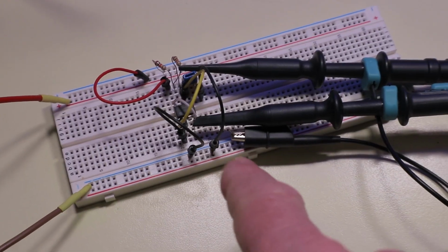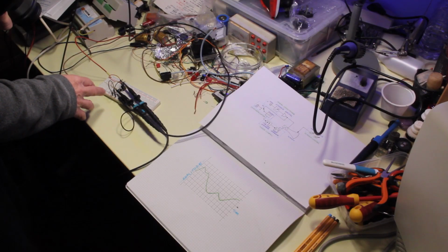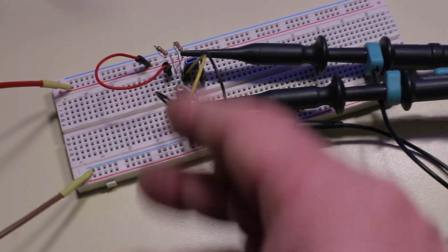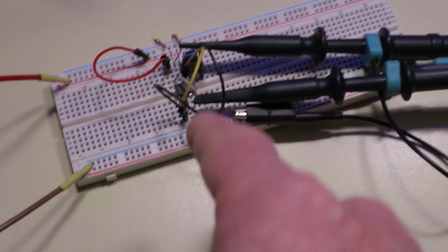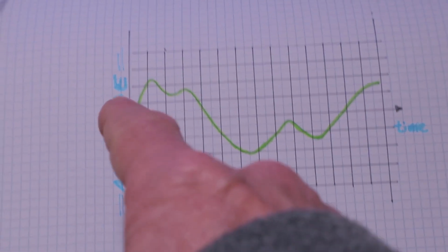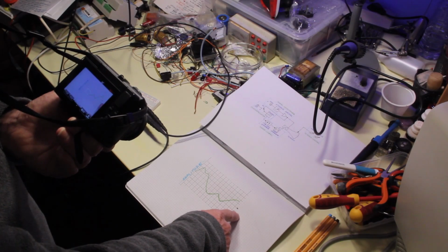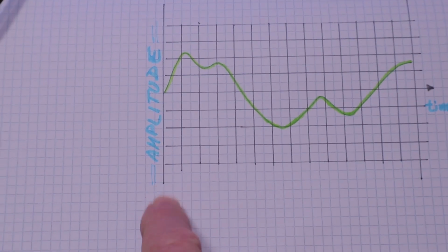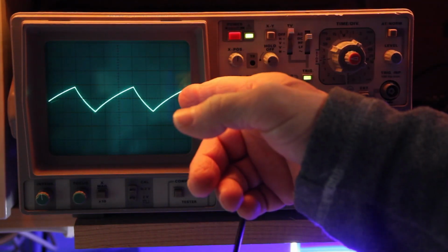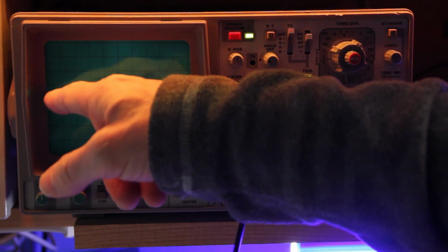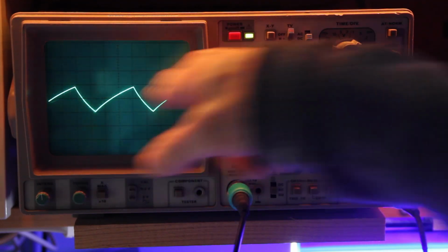When we analyze a circuit and we want to analyze a varying value over time, let's say voltage, we take that varying value and put it on a Cartesian plane where the x-axis represents the time and the y-axis represents the amplitude. And this is what an oscilloscope does, sweeping a luminous dot across the screen.